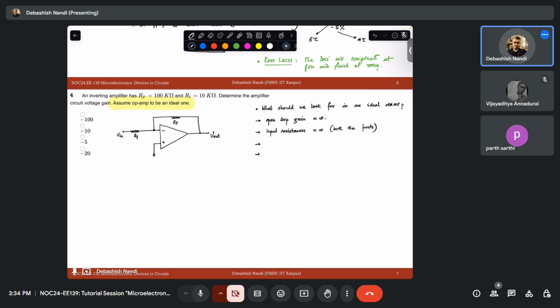Not necessarily. What if there is a feedback with drain, input and output? Suppose if I give you some kind of circuit like this, this is your input, but there is a feedback connected. So will the input impedance be infinity? No, sir, it will not be, right? So it doesn't matter whether it is a gate or not. There may be another parallel branch. You never know. So do not be misinformed about this thing. Okay.